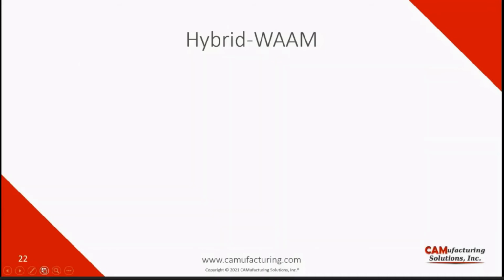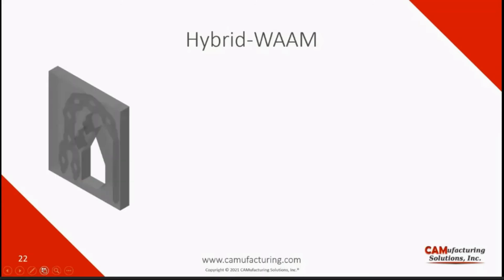Therefore, we did design a mold, and in order to design a mold, we had to design cooling channels as well. So what we designed is a mold block and a cooling channel block, all made by additive and hybrid manufacturing processes, and it's all one part. But how do we build it? So this is the design of the cooling channel. As you can see, it has been designed in a way that there is no overhang angle if you put it on this surface. So this cooling channel does not have any overhang angle.